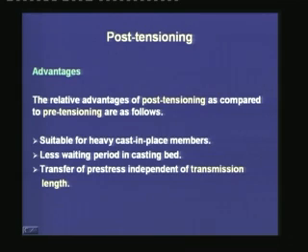Next, compared to pre-tensioning, post-tensioning has a shorter waiting period in the casting bed. I mentioned earlier that for pre-tensioning, the pre-stressing bed is occupied by the concrete member till it attains the required amount of strength before the transfer of pre-stress. This can be a hurdle when there is a high demand for the pre-stressed members.